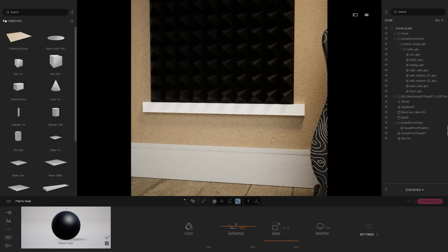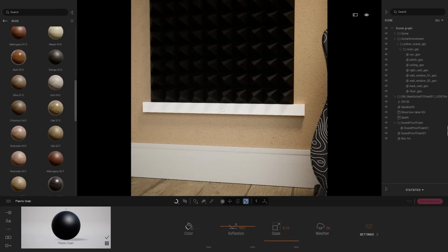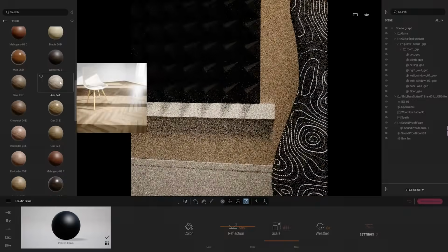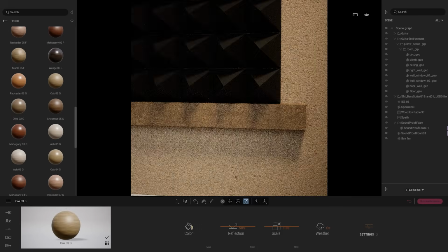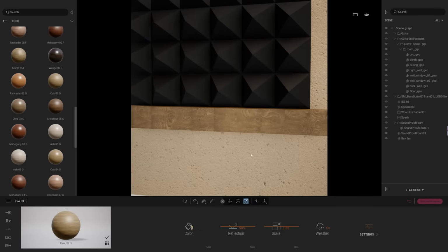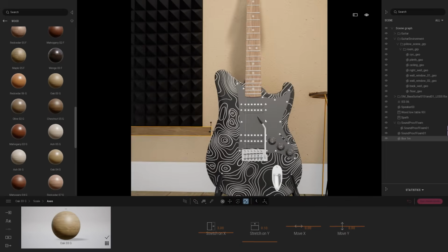So now that's done, let's come back to the material, wood. Towards the bottom, we have some seamless wood. At the top, it's mostly parquet type of wood, but here we have some seamless wood, so I'm going to drag that one on the side. Coming to the more, it should be rotated 90 degrees, and since I've stretched that geometry, I will also need to stretch that texture to better see the vein of my wood.